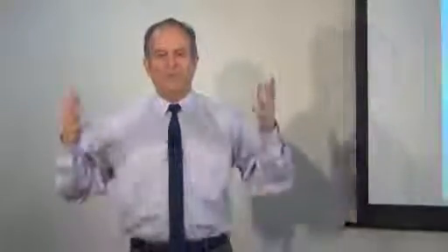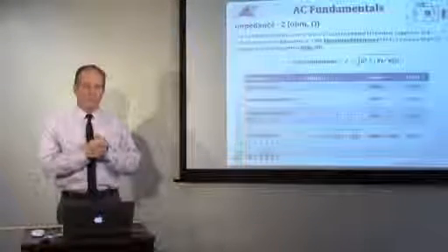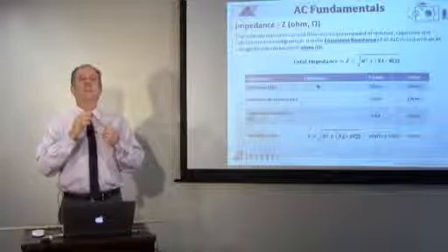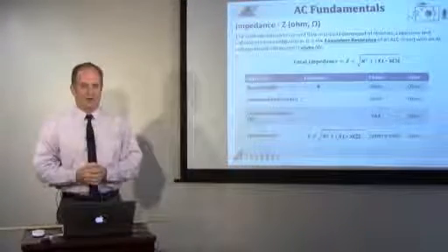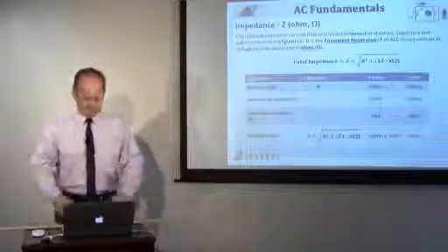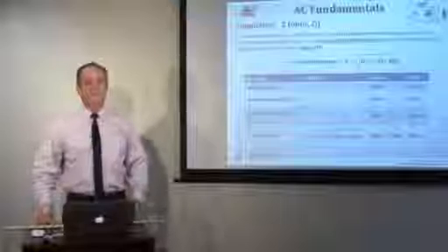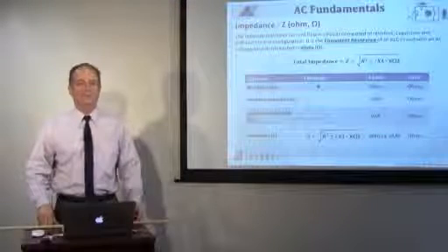You're going to start picking up all these terms as you go through these courses. This is a fundamental course. It's trying to give you a foundation. And when it comes to impedance, like we're talking about here, this pretty much puts the power lines and the transformers and the capacitor banks and all that stuff into perspective. We're dealing with ohms, but in power we're talking about watts and VARs. Plus or minus VARs can cancel and give just watts. Okay? So, just a little bit of added information on this particular slide when it comes to impedance on AC circuits.